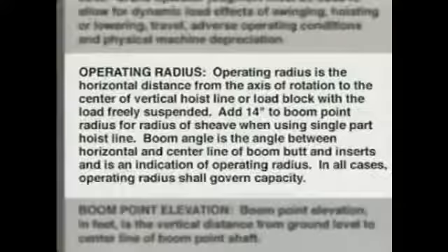An important consideration during any rigging job is making sure that the load is properly balanced. Load balancing involves equalizing the weight of the load at various lifting points. Distributing the load's weight in this manner helps prevent the load from bending, breaking, or falling.